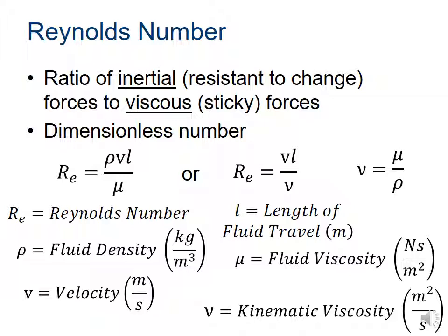This is how we can use a wind tunnel to compare the characteristics of a model airfoil or other device to a full-scale model. Sometimes engineers can't get the air in the tunnel moving fast enough, so they can apply this practice using water. Water has a much greater fluid density and viscosity, so they don't have to get it moving as fast to achieve the same testing conditions.